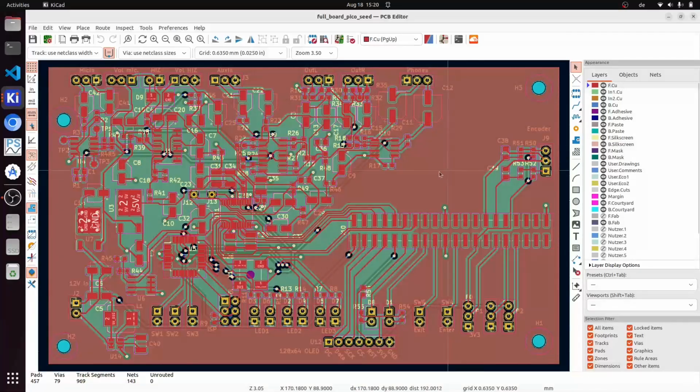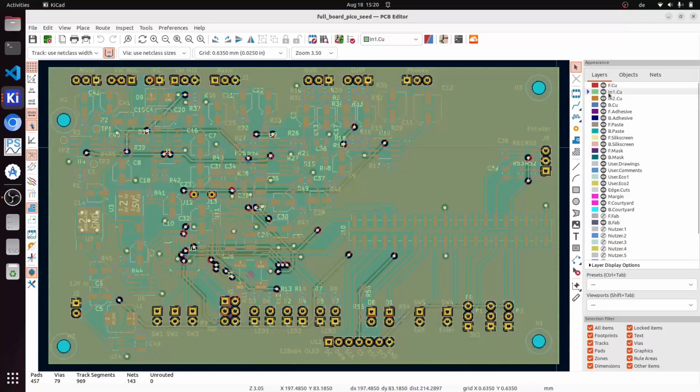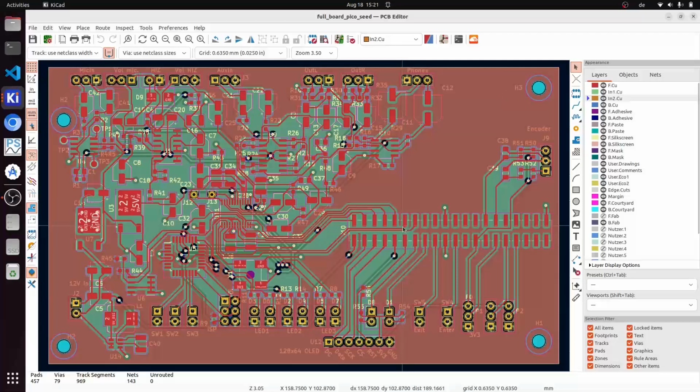So on the front layer is just the main connector. I first of all tried to put as many connections on the front part. Where this is not possible, where traces need to cross, I also switched to the back layer here, which has much fewer connections than the front layer, and one of the inner layers is then the ground plane. Well, that's about it regarding this board.